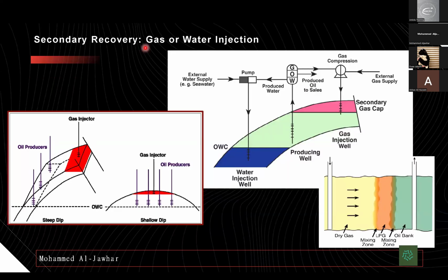So as mentioned, for secondary recovery, is it gas or water injection, and where you have to put your wells to get the most out of the wells you need, and how you can maintain your pressure.